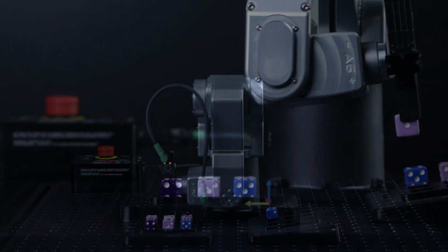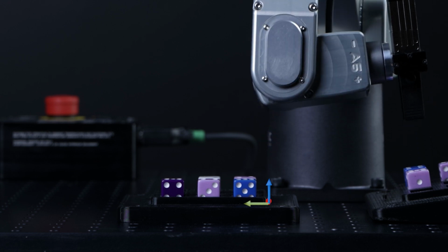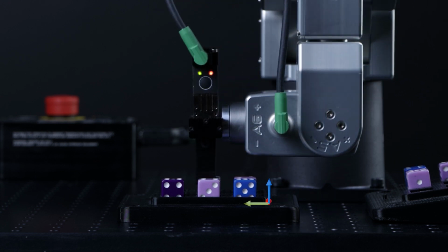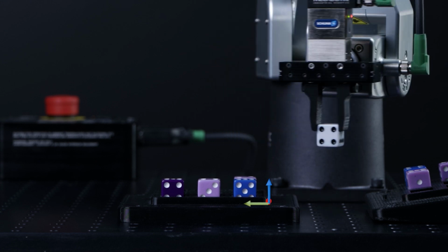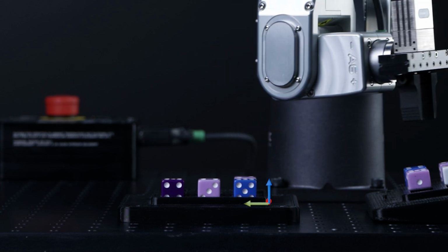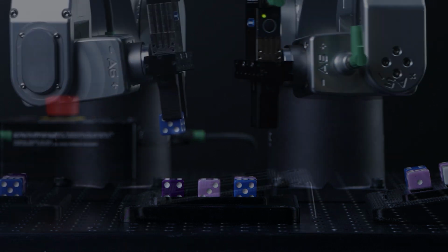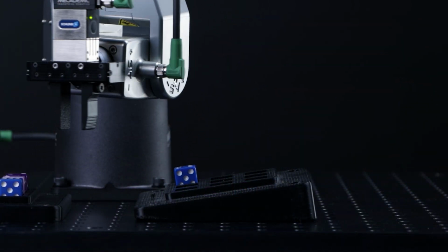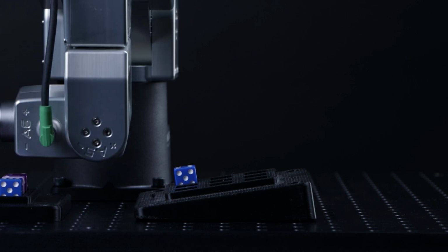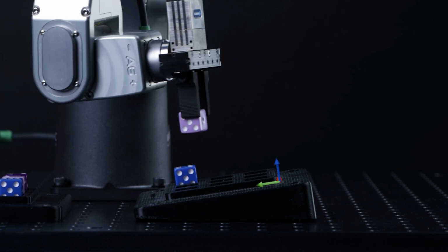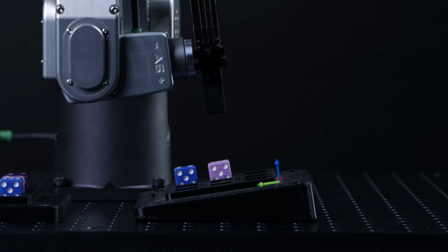This is a typical scenario, and if we didn't place the WRF in the corner of the pick tray, all the 9 dice positions would have to be taught individually. Instead, we can calculate the poses of all 9 positions by using regular increments in X and Y. Now, most importantly, to define the 9 dice positions on tray 2, where we want to place the dice, we only need to redefine the WRF at the corner of the place tray, and then reuse the Cartesian poses from the pick tray.